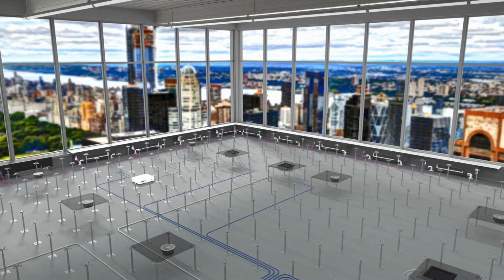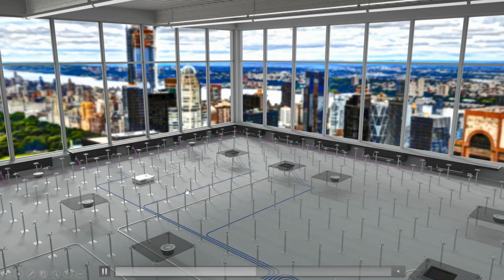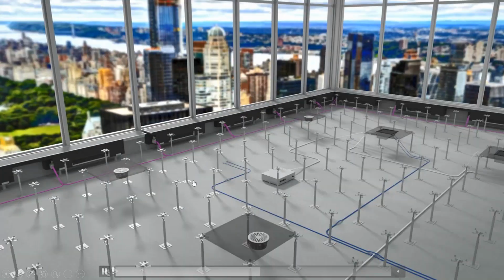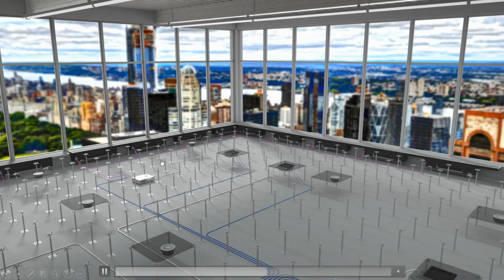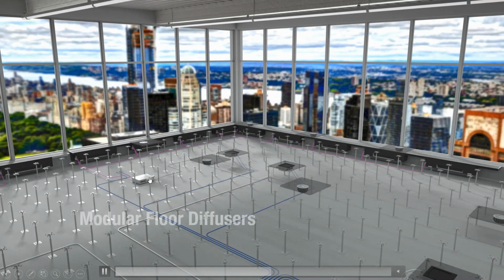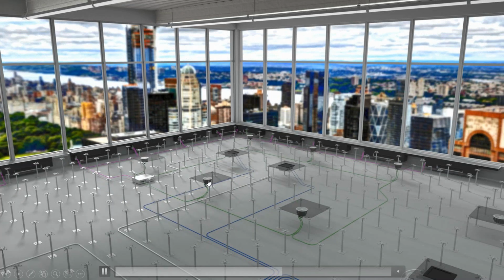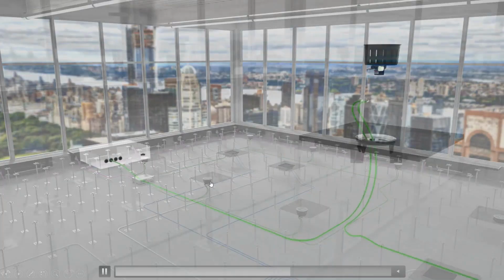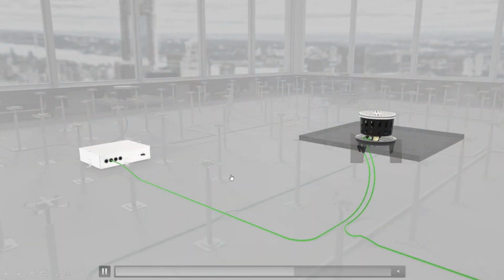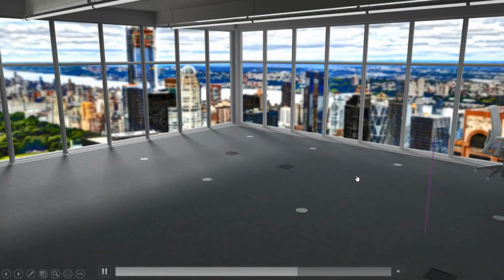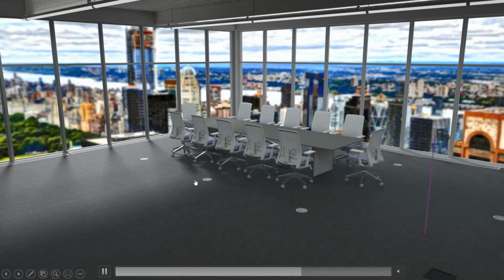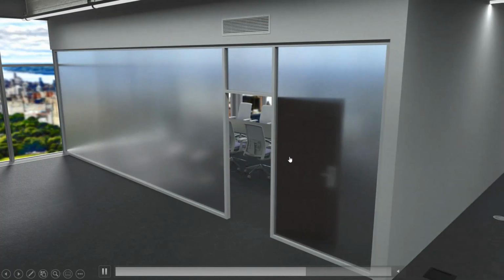So notice we're using existing materials here from that open office plan. We're going to move the round floor diffusers and replug in the perimeter heating devices into that control module. Here we're going to use the existing diffuser face and ring and drop in new VAV baskets into those rings that are mounted in the floor. And so that way you get VAV control. It's all plug and play wired back to that control module, and then ultimately controlled through a thermostat.